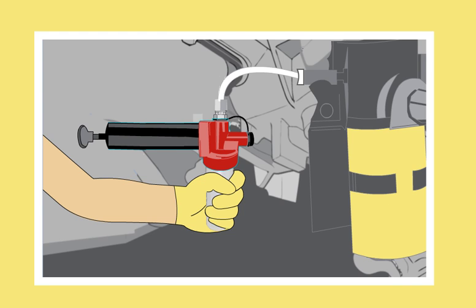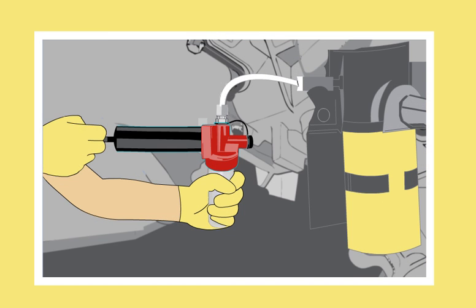Be sure to wear proper PPE, including gloves, when pulling oil samples. The oil will be hot, and the tubing and sample bottles are not insulated, so wear gloves to adequately protect you from hot oil. Now, push and pull the vacuum pump plunger a few times to start the suction.